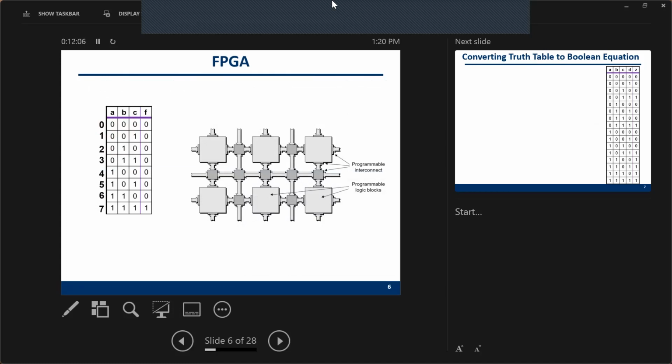In this way, it's possible for you to directly store this table in some memories, in some buffers. This is the so-called FPGA. It's reconfigurable. Why? Because you can change the values of your truth table. For example, you can write this 0 and 1, and then you just do the reconfiguration.